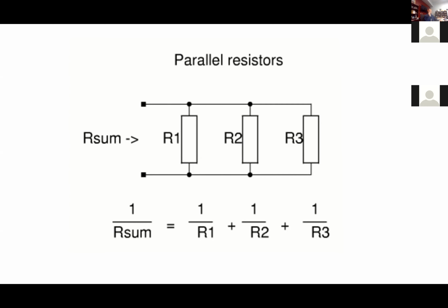So one of the uses of parallel combinations, if you use 2 or more resistors in parallel, because current splits off in a parallel circuit, you'll have the same resistance value that you've used your combination to find, but the current splits off amongst all the resistors. So each resistor is dissipating less power rather than one resistor dissipating large amounts of power, which reduces your chance of the resistor burning out. Same resistance, less dissipation in one resistor means less chance of overheating, is a good way to think about it.